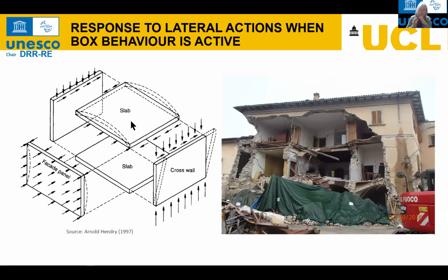This is all fine and well, and indeed the roof, as you can see in this particular picture here, can be quite stiff and rigid, but if it's not appropriately connected to the facade, and if the facade doesn't have a level of internal connection to the masonry and to the party wall, this is how we end up.